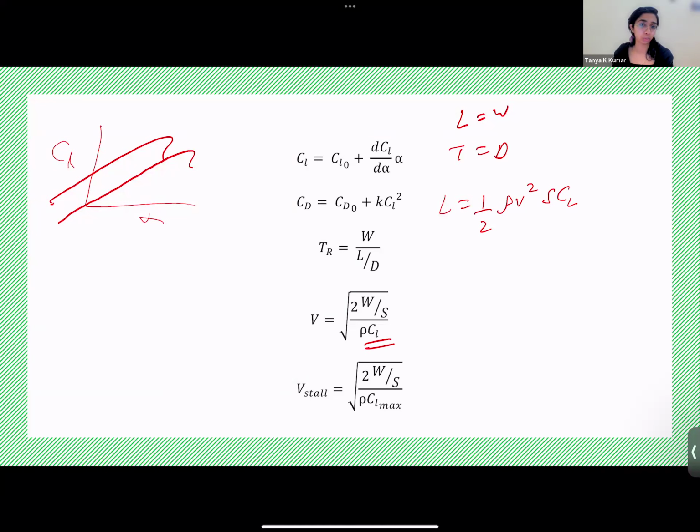We discussed what stall was in the last class. So can anyone recall it? What was stall? You can either type it in or unmute yourself and let me know. What do you remember by stall? The angle of attack where the flow separates and there is a fall in lift. Yes, okay. Stalling is the condition where there is boundary layer separation, or flow separation, and there is not sufficient lift to balance the weight. You're absolutely right.